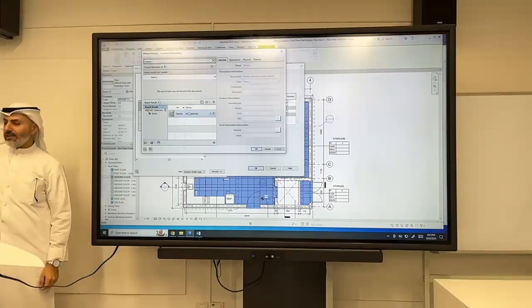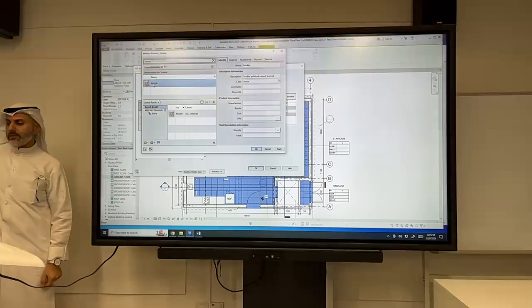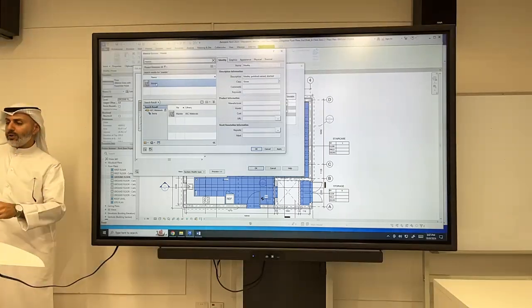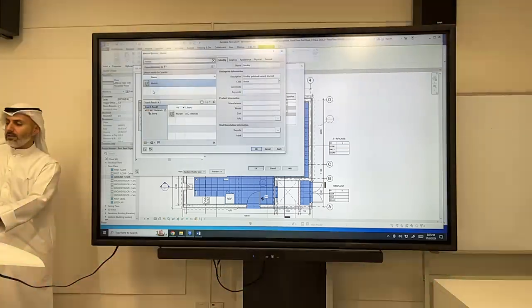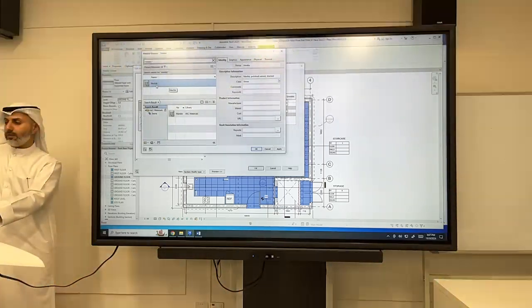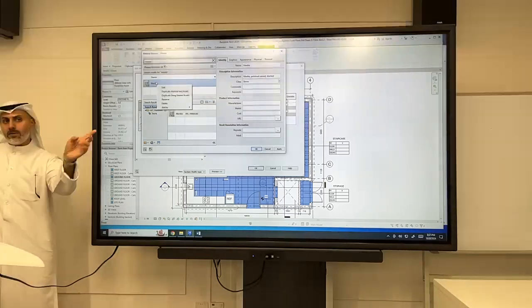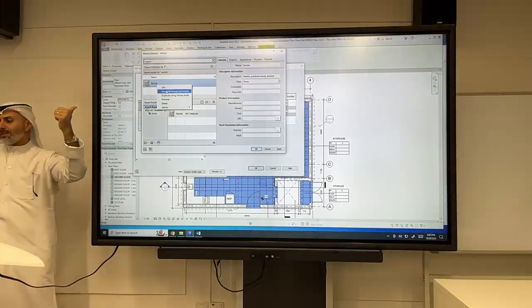Okay. Click on marble. But then there are 2 arrows here. Click on the one with the pencil. And that will take it up here to edit. Okay? You can then right click, duplicate material and assets. Then do this to the travertine. So right click on marble once it goes up there. Duplicate material and assets.